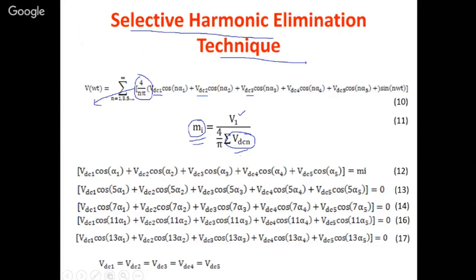But when you go for a 3-phase system, automatically the third harmonic will be eliminated, and the even harmonics are also not there. Not all the multiples of third will be eliminated, though. You will have the 9th and those others. In the case of a 3-phase system, which is the deadliest harmonic? Fifth is the deadliest harmonic.